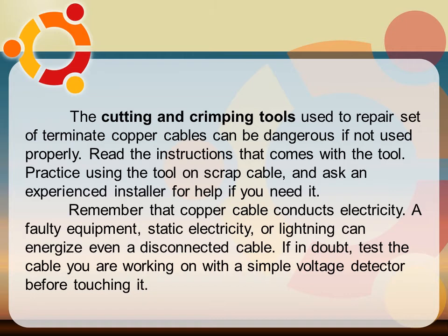Remember that copper cable conducts electricity. Faulty equipment, static electricity, or lightning can energize even a disconnected cable. If in doubt, test the cable you are working on with a simple voltage detector before touching it.